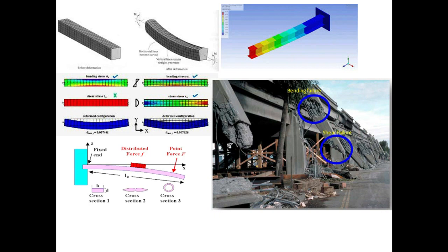or if you have an I section beam, as you can see in here, the bending stress profile will be different because it depends upon the material, it also depends on the loading, and it is also hugely dependent upon the specific cross section. So what we are always interested in, as I've told you, is that the deflection configuration is very important. Because of this movement, what is going to be the deflection about the neutral axis, and we are interested that this deflection should stay within the elastic limits, and we do not go into a yielding zone. Otherwise, it might result in a failure.